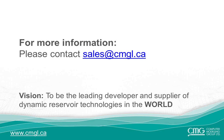The next question is from Gerardo, and he would like to know, can you elaborate a bit more on how CMG approaches the fracture propagation? Is it entirely dependent on the Barton-Bandis model, or do you use some other way of doing it? Currently, it will be based on the Barton-Bandis model. So like I said earlier, it will depend on the stress regime in your reservoir. So we can set in our initial stress conditions, and then as we inject the fluids, the simulator will monitor the stress conditions, and if it goes over a certain threshold, then we'll have fracture opening, which would then change the permeability and properties in the reservoir.